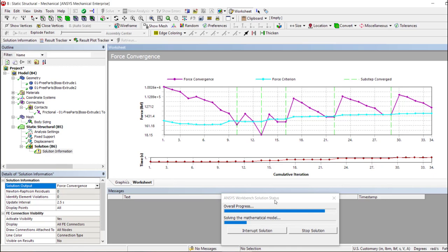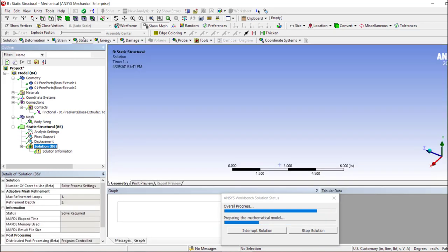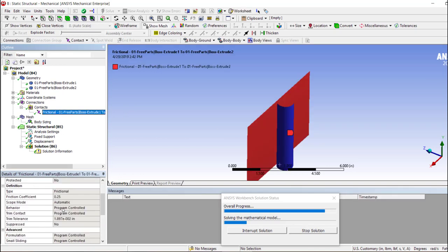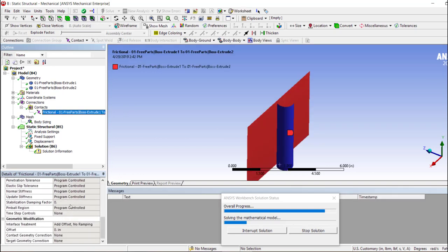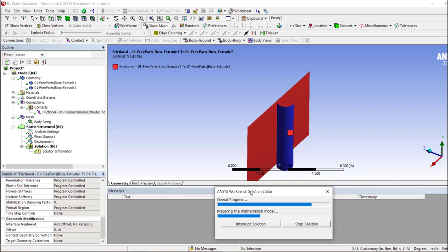Now when the solver is running, I cannot check the results in Ansys. I cannot do anything until it finishes, and then I can see where the results or the trends are going only after it submits all of its results. But that doesn't happen in Abaqus. In Abaqus, I can check the results while it's running, and I can even fix these things, go back, kill the job, and change everything. Otherwise, if some of these things are wrong, I would have to wait until it's too late.